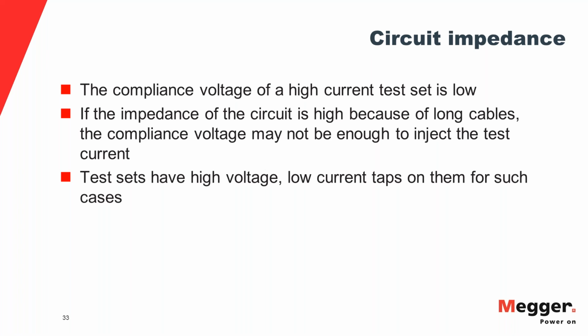How do you deal with this situation? There are different ways of dealing with high circuit impedance. Some test sets have high voltage, low current taps. If you can run the test using those low current taps, then you can use those taps for running the tests on circuits with high impedance.